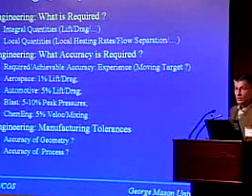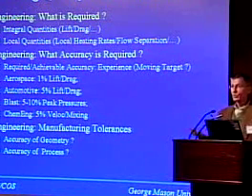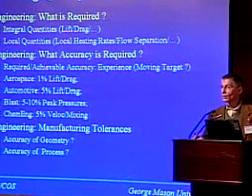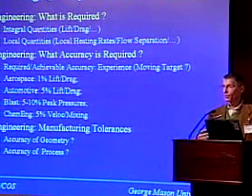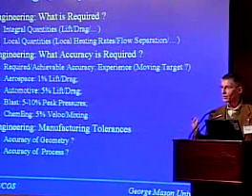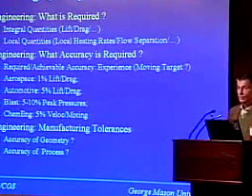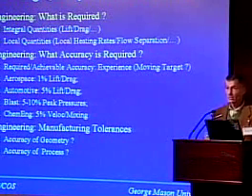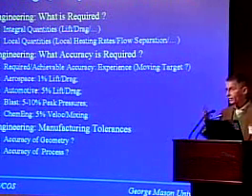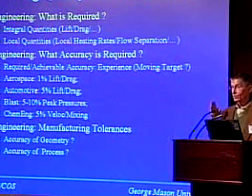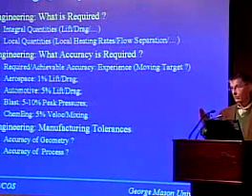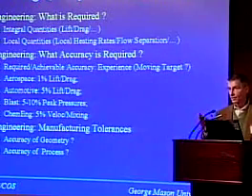And if you are in the aerospace, particularly in the commercial aerospace, 1% more drag is a deal breaker. So you need to know your drag to at least 1% if you're going to convince a potential customer to buy your airplane. If you're in the car industry, 5% lift to drag is absolutely acceptable. Now it's a bluff body, the flow fields are not streamlined, so even to get to a 5 or 3% drag prediction is quite difficult.